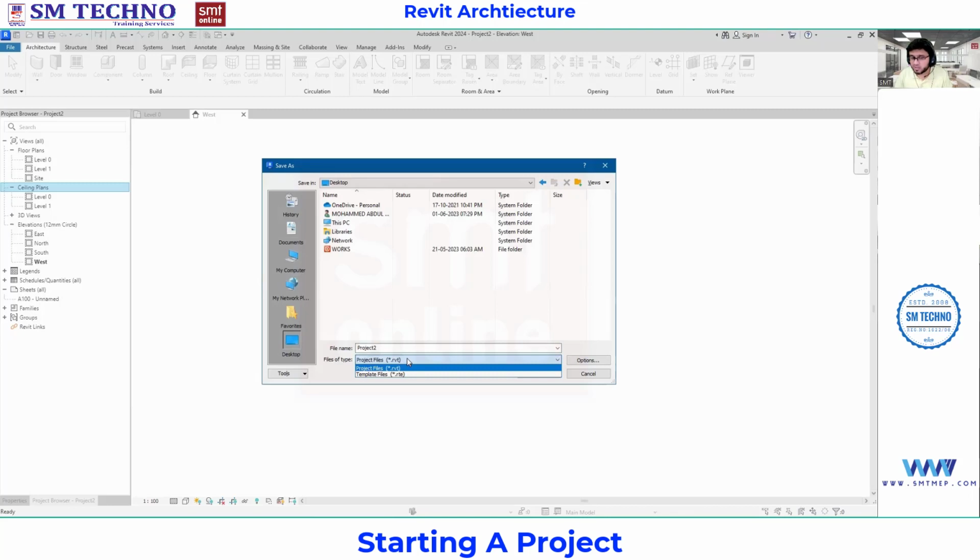If you want to save the same project file as a template file, you can also change it from here. But by default, we won't go with the template format. We will always go with .rvt. But if you want to keep some similar things in the project, in that case, you will save your RVT into RTE. That's the secondary case.